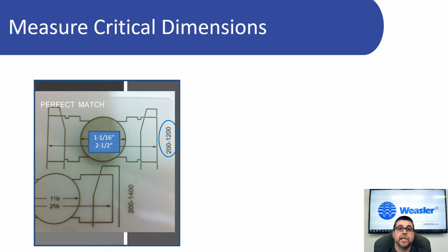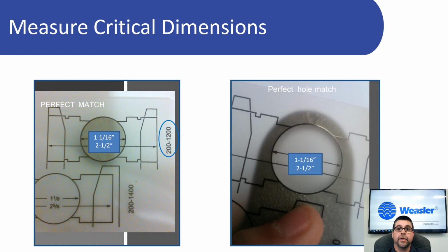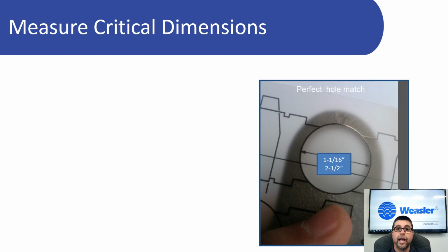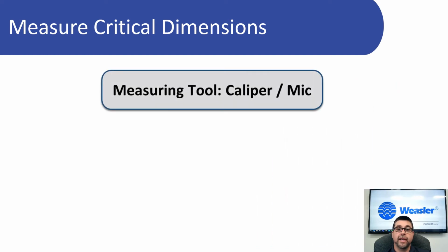The transparent cards can be placed directly over the cross and bearing kit until you find the correct size that matches up. The yoke ear hole can also be used to identify the size. Note that the TIS cards contain the actual measurements and cross and bearing kit part number that has been identified. A caliper or tape measure can also be used for identification.